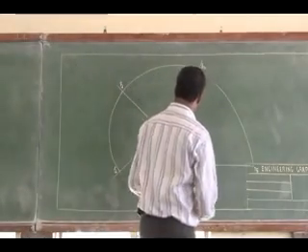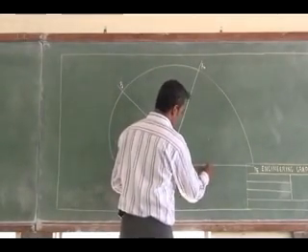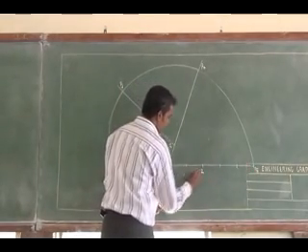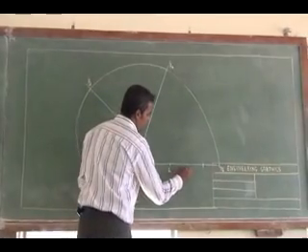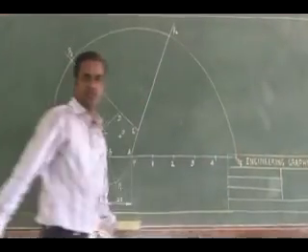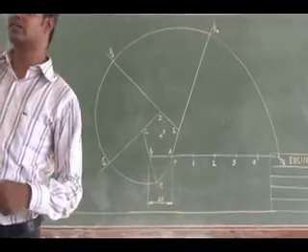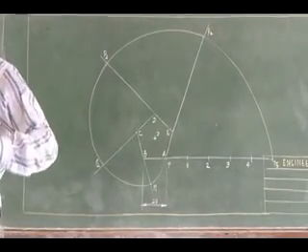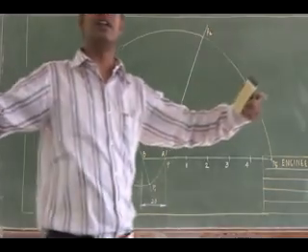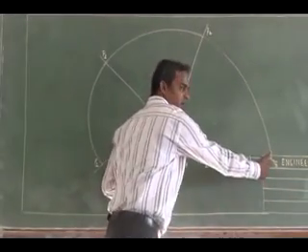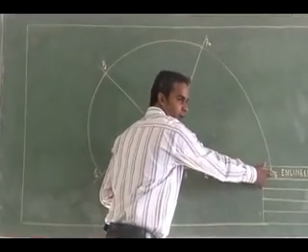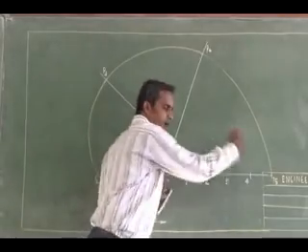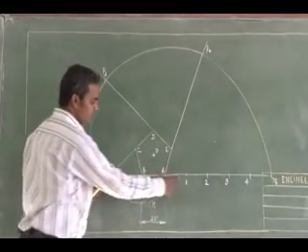So what you can do, otherwise, I can divide this line into 5 segments. Say this is 1, first one, second one, third, fourth, this is the 5th division. So for any pentagon, polygon or circle that is given, you can draw a horizontal line for a length of its circumference. What is this length? It is the length of this circumference, 100 mm. How many sides do you have in your polygon? I have 5 sides, so here I have divided it into 5 divisions.